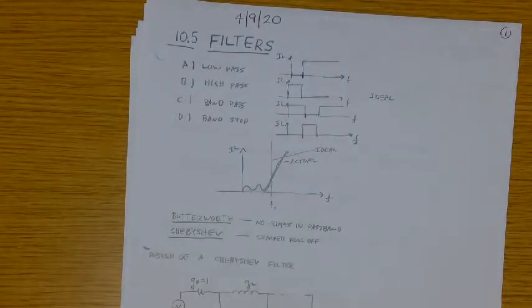What do you need filtering for anyway, right? Let's zoom out for a moment and discuss that. Well, obviously, one application is in modulation and demodulation. If you have a signal that's coming into your receiver, typically you multiply that by some intermediate frequency to shift the information to a lower frequency. But in that multiplication, you'll have higher frequency components too, and you may want to eliminate those, so you may want to pass the product through a low pass filter. That's just one application of filtering.